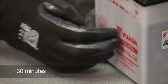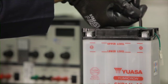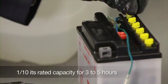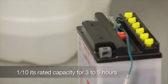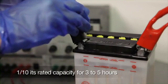Leave the battery for a minimum of 30 minutes, gently tapping occasionally to remove any bubbles trapped between the plates. If after 30 minutes the electrolyte level has fallen, top up to the upper fill level. Replace the filler caps loosely and begin to charge the battery at 1/10 its rated capacity for 3 to 5 hours. Charging at a higher rate could damage the battery.